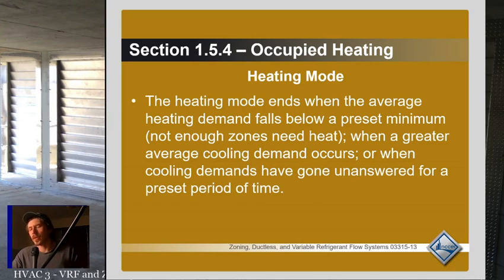And this is kind of special to commercial systems, right? In a lot of commercial buildings, you need cooling almost year-round, especially in larger buildings. The larger the footprint, the more likely you are to have this issue, because you only lose your heat to the outside air, but you can gain heat from people, equipment, lighting, electronics, whatever. So you are more likely to gain heat in a building than you are to lose heat from the building.